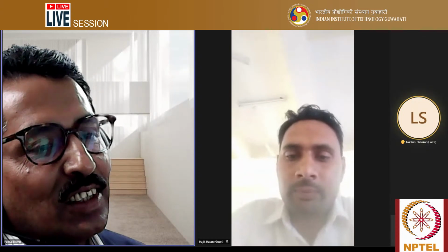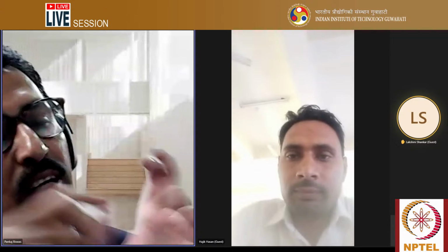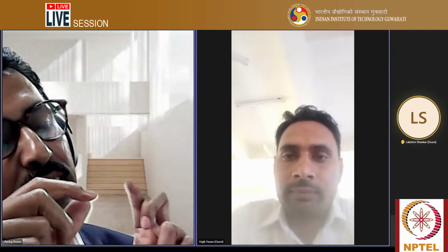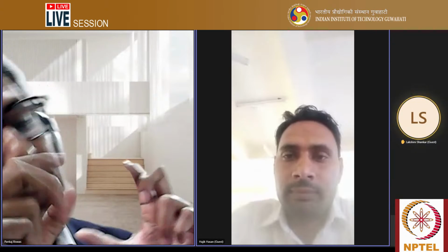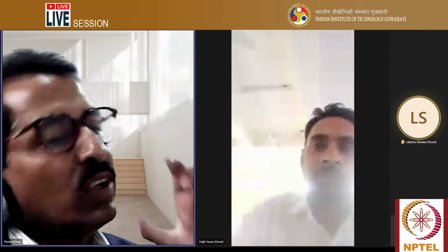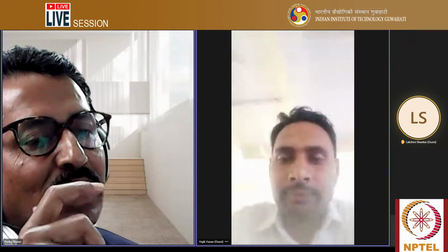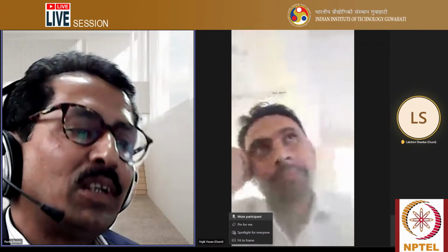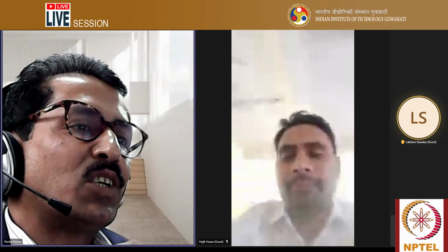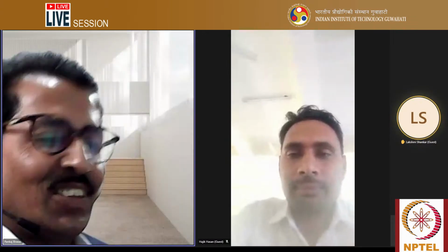Clear, Lakshmi? Yes, sir. Always keep this in mind: the higher the length of stick out, the more your arc length is generally reduced. If the arc length is reduced, the heat generation in the arc region will be less. The lesser the arc length, the lesser the heat generation in the arc. Clear? Fine, that is the thing.